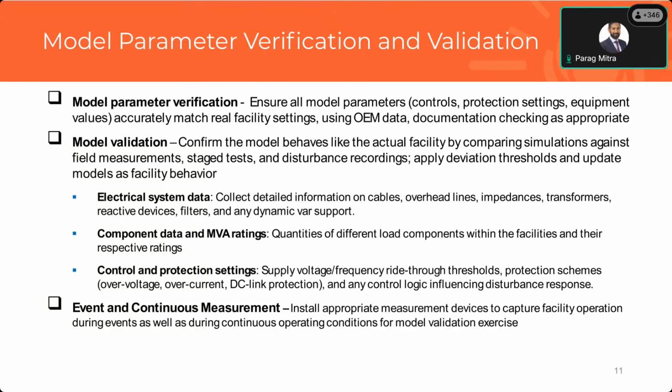Model development is important, but verification and validation of this model is important as well. There are a few items that need particular attention here. One is model parameter verification. This is an exercise where we ensure that all model parameters actually match the facility settings and the facility ratings. They are generally done using OEM data, and it is very important to have documentation to make sure that the parameters that have been provided with a certain model are actually verified.